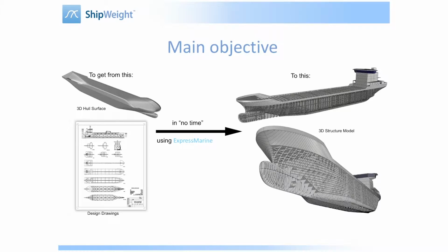And so we do it really fast, with the sole purpose of the weight and CG. So we're sacrificing something here. We're not doing any details. We don't care how the stiffeners stand towards the shell. We don't care if the stiffener is normal or horizontal to the shell. Just in the grand scale of the weight and CG, it doesn't matter.